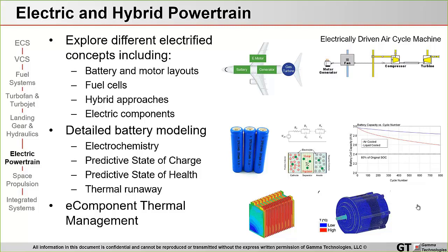Now, in terms of batteries, we realize these are becoming more popular, particularly for eVTOL aircraft and so forth. For batteries specifically, there are detailed levels of analysis that could be studied in GT Suite, including the ability to do electrochemistry. That allows you to predict the performance of the battery instead of necessarily relying on an electrical equivalent map from test data or from the supplier.